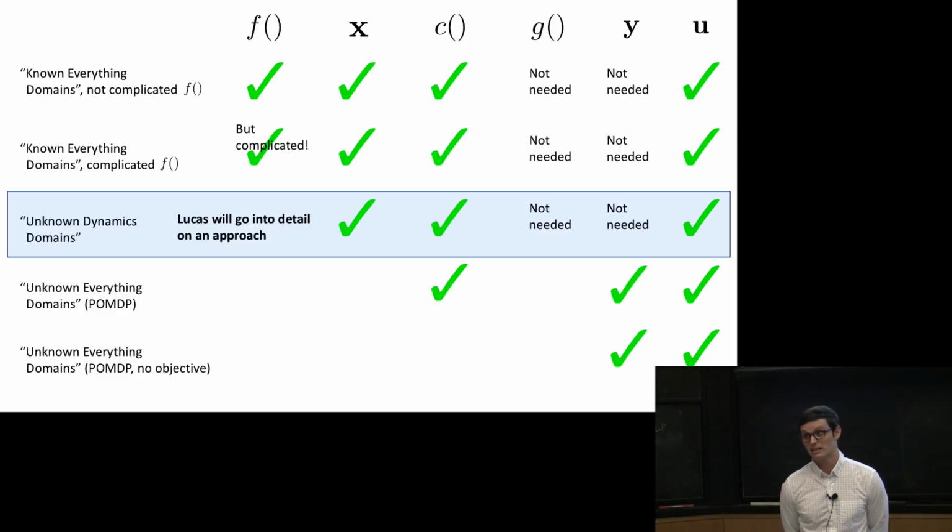So definitely on an airplane, you have to estimate state. Like, you don't have just some magical thing that says, here is exactly your velocity and your position in the world and things like that. On an airplane, state estimation is what people do. They estimate the state. You can use what's called pitot tubes to estimate your airspeed velocity. But it's going to be noisy, and so there's a lot of good state estimation work in taking noisy measurements over time and fusing them and getting a good state estimate. So yeah, when I say that, on a plane, we can just know X and we can apply Lyapunov stability analysis, that is including state estimation, yes.